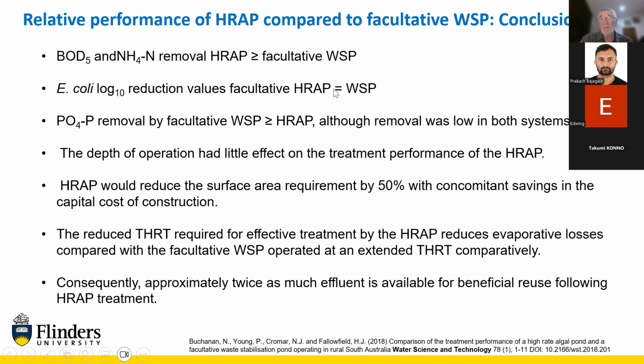We got the same disinfection between the systems. We got the same phosphorus removal in the system. We showed that the depth of operation of the high rate pond had little effect on the treatment performance. We then started to look at the surface area requirements. For the same volume of effluent being treated at a 5-day residence time, the high rate pond would easily be half the size.